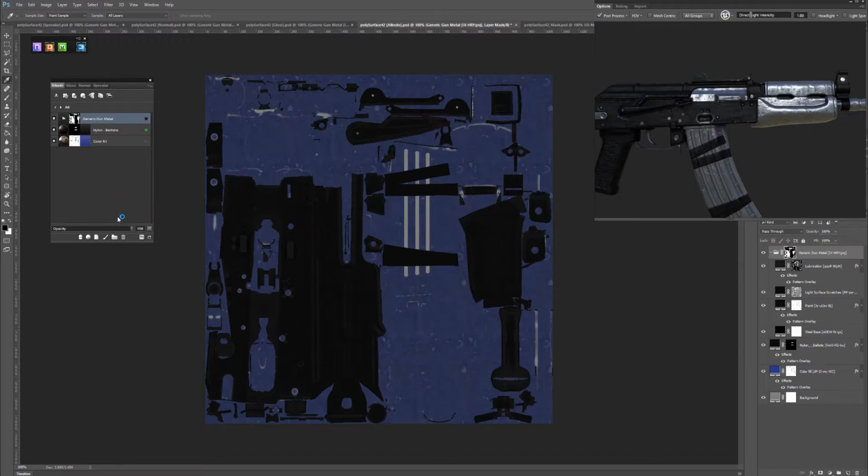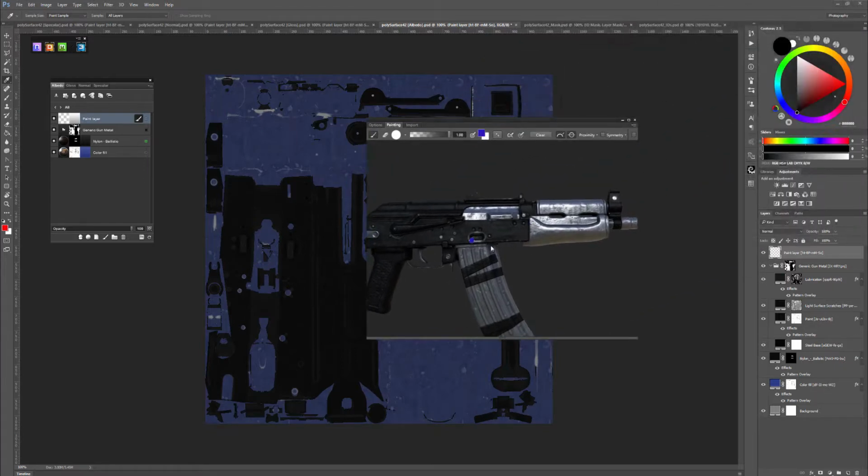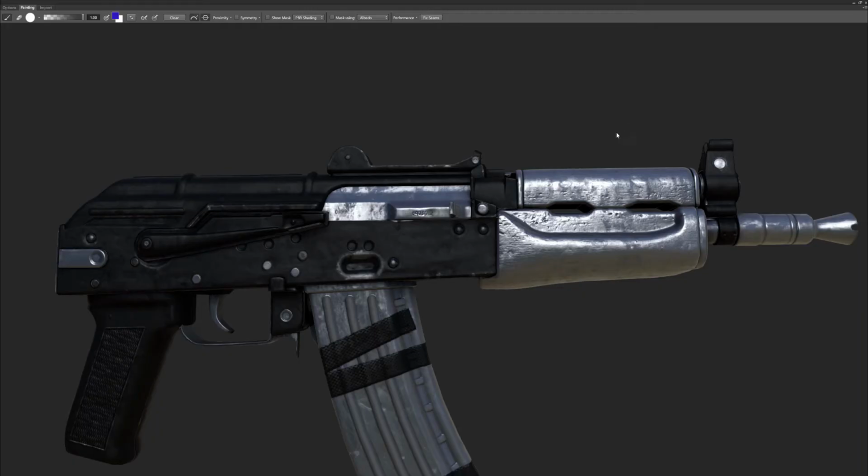Okay, so let's go on to the next piece. Let's add a color paint layer. Clicking on that, with this layer you'll notice it's pretty similar, but it has this toggle paint mode button on. If I hover over here, nothing really changes, but if I hover over my 3D object, let's expand this out for the stem apart. If I start painting or clicking and dragging, I can paint directly on my model.